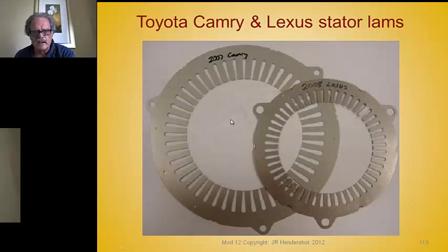I'm not sure. But I think what's interesting about this is they have added places for welding this core on the OD. I don't think that's necessary, but they've added it there. They would laser weld that and melt this little protrusion together there. And I guess they got enough yoke thickness they could do it, but notice they put it over the center of it too.